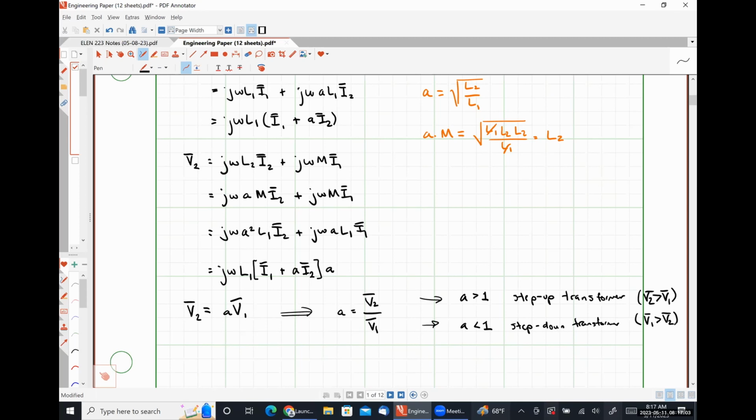What about a step-up transformer? Yeah, so effectively, when we generate voltages using three-phase generators, we're probably not able to generate hundreds of kilovolts. So we typically generate something on the order of tens of kilovolts in our power plants. We step it up to really high voltages, as much as 250 kilovolts RMS, to transmit it over very, very long distances. And then once we hit a substation, we step it down to a safer level for being around humans. And once we get it to a household, we step it down to an even safer level for people to interact with regularly. Absolutely right. So step-up and step-down transformers form the fundamental basis of power distribution in every industrialized country.